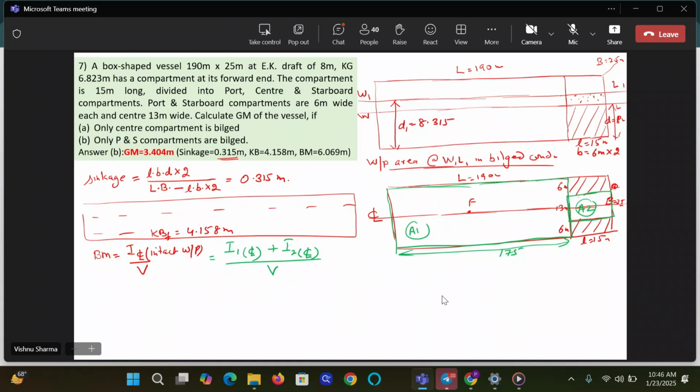Yes, correct, guys? That will make things easier for me because center line is a standard axis for both of them, A1 as well as A2. So I don't have to use theorem of parallel axis. So it is only to avoid the use of theorem of parallel axis. But don't worry, I'm going to give you a question for homework where there will be no escape.